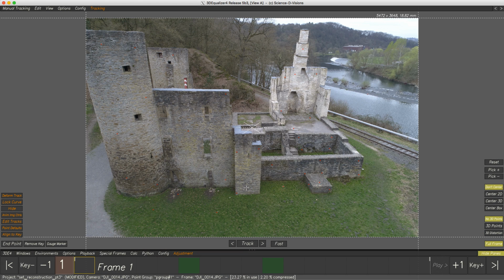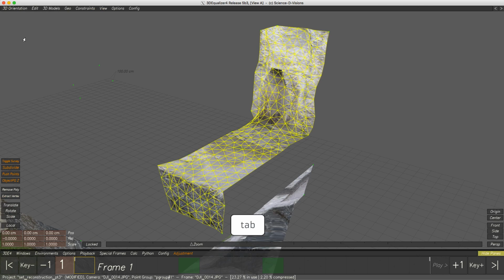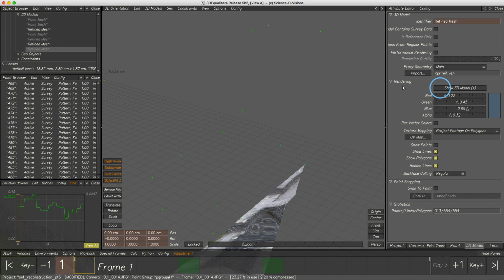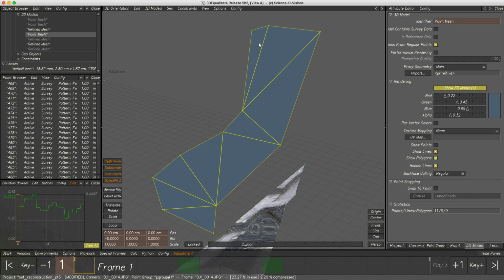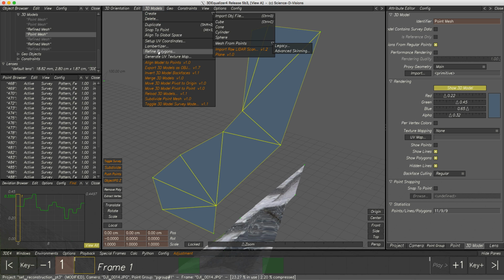Unlike the wall in front of the castle, this white tower and ground are very far away from the camera. Therefore, the actual amount of pixels available for this area are quite small, which in turn has a much bigger influence than a refinement of an object close to the camera. Let's have a look if we can handle this with a different setting in Refine Polygons.